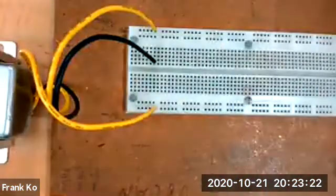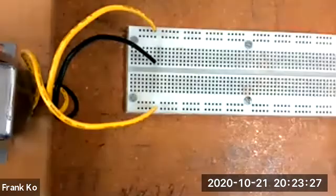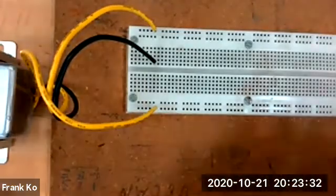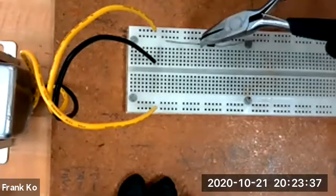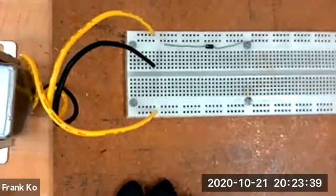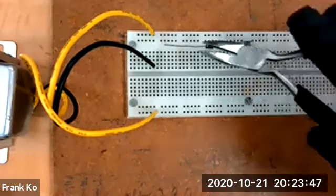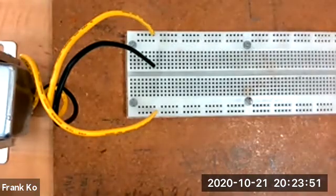Nice. All right. With your needed parts, grab a 4001 diode. A 4001 diode looks like this. It's a black cylinder with a silver stripe on one end. The silver stripe is your cathode. And we will go ahead and place it on our board in this fashion.